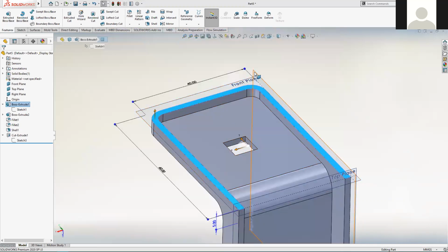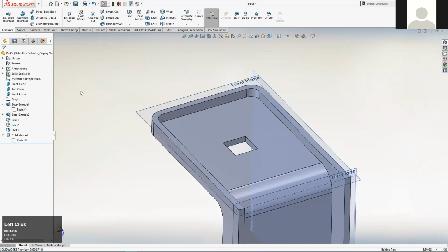just like all the base planes like this front plane and this right plane and this top plane. As long as the face that you pick is perfectly flat and planar, the system is willing to regard it as going in all directions infinitely. So it's infinitely large. So that's why you can sketch in the middle here, even though that face is a very thin 2mm face. So it just regards it as a plane, essentially.